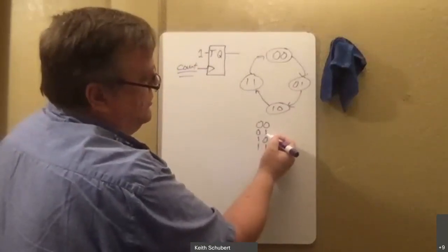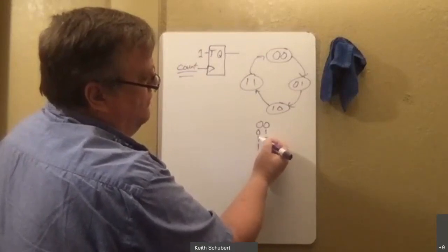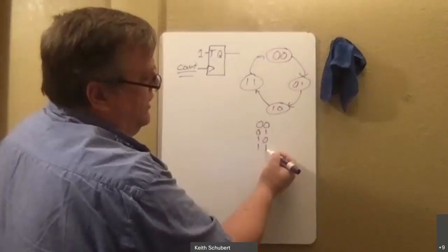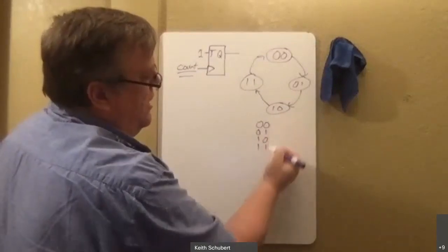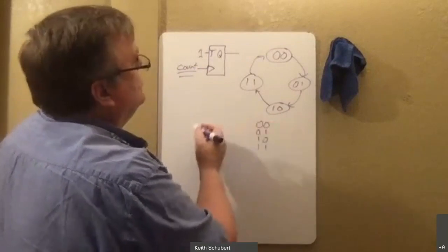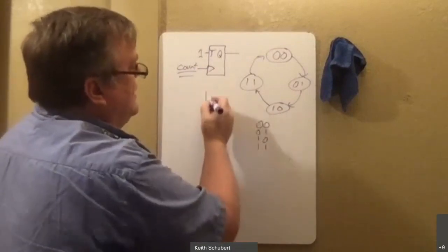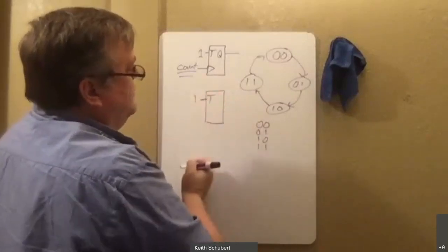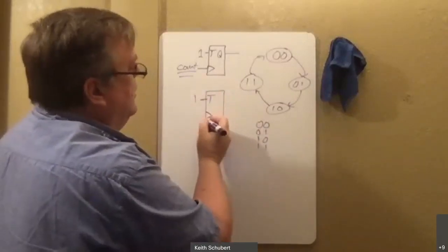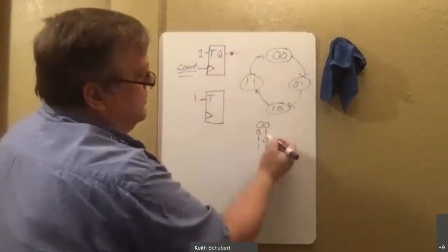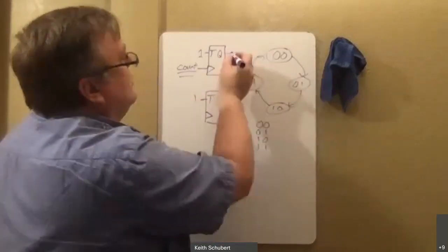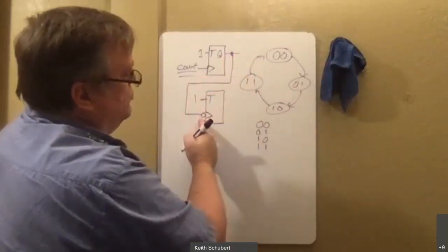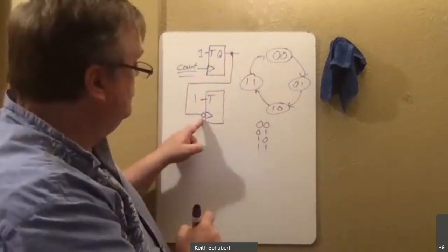Because this is on, when it turns off, this one turns on. This one is on, when it turns off, coming back to the top, this one again toggles. That means the second bit is also a toggle flip-flop that is set to toggle all the time, and its clock just looks at the previous bit and toggles whenever it turns off.